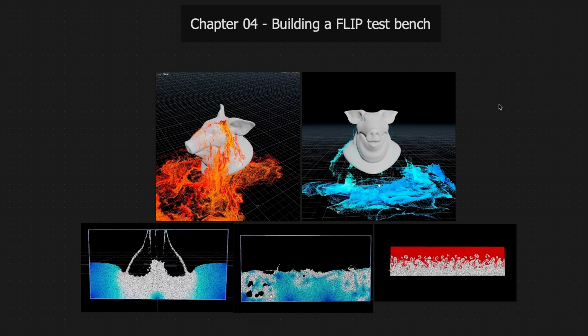And the next chapter is a bit more comprehensive chapter about the FLIP solver in Houdini. In here, we'll go through almost all of the settings in the FLIP solver, and we'll test multiple settings to see how we can use that later on in our main shot that we'll create. But this is where we also test multiple things that might be useful for you, like viscosities and divergence and air incompressibility and densities and so on.